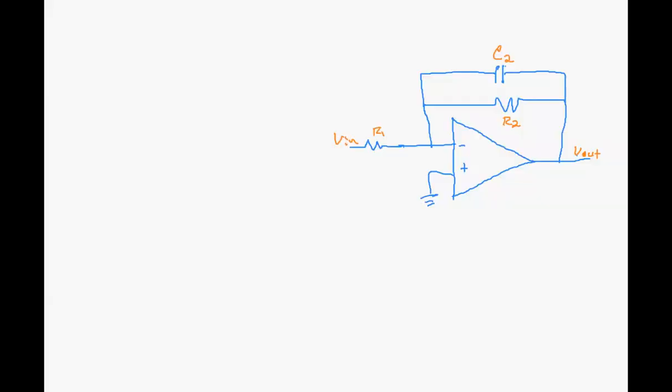It's important to understand how easily you can solve some circuits by a transformation. In Circuits 1, we may teach you to always solve parallel resistances, but sometimes it's much easier to solve a parallel conductance. It's always easier to solve a parallel conductance. And if it's a capacitance, then we might want to use an admittance.